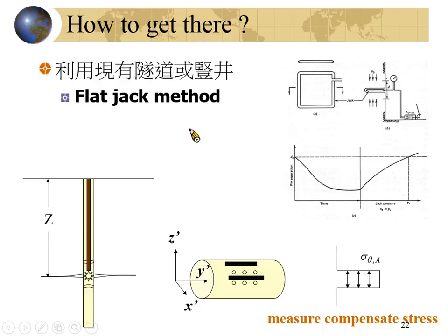Okay? And you will insert a flat jack. Do you know a jack? When a tire of your car is broken, you need a jack to lift the car and change the tire. So you will put the flat jack here and try to increase the pressure. The jack will make the slot open again, so you will measure the displacement.